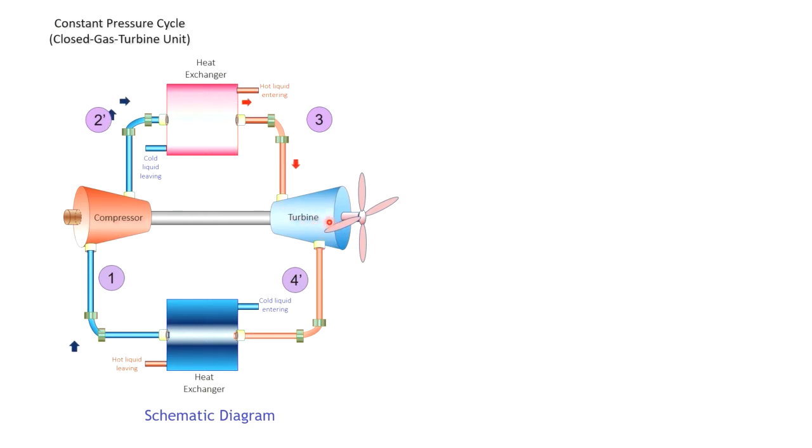After that, a certain amount of work, or a very low percentage of the heat energy in the air, will be converted to useful work, like generating power or moving a propeller. After isentropic expansion, the energy which cannot be converted to useful work has to be rejected to a lower temperature region. That is why it enters a cooler and undergoes constant pressure cooling. Then it goes back to the compressor again, where it undergoes a full cycle.